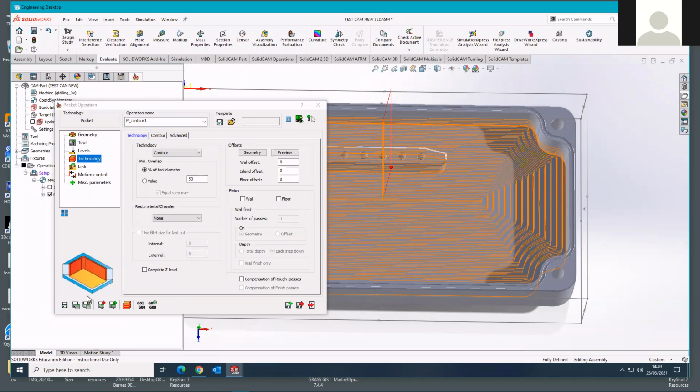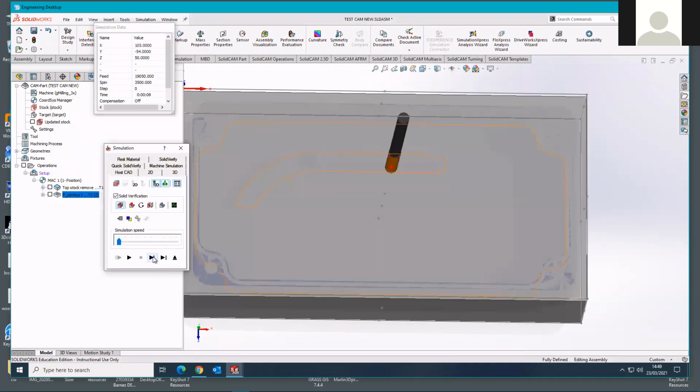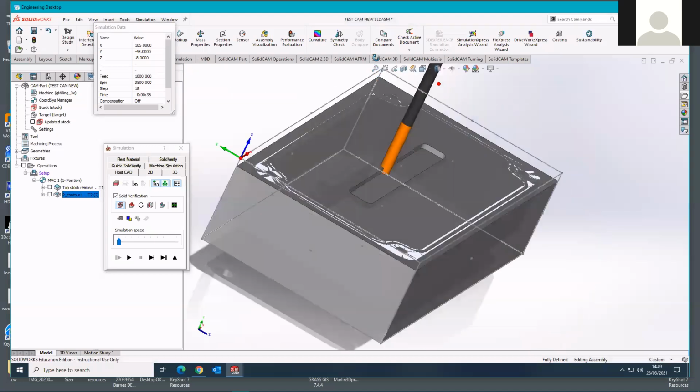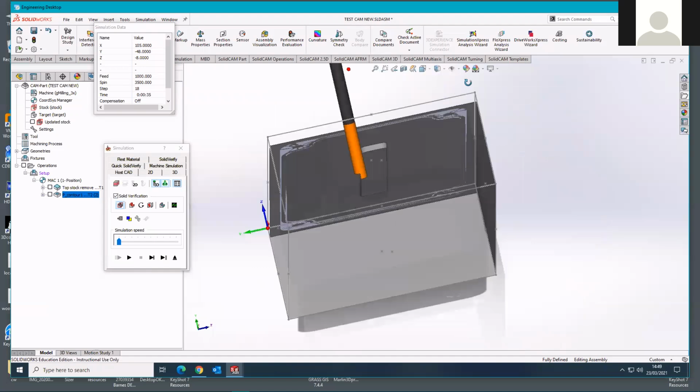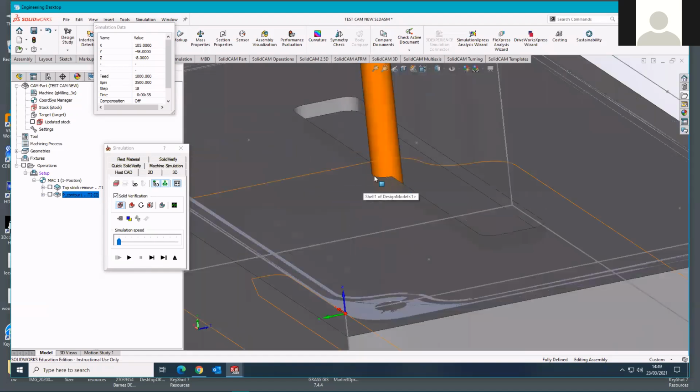So when you think you're removing material and you believe the tool should be held vertical, the actual condition on the end of the tool is that it's not vertical. It's been deformed slightly, like a banana shape. So it's been pushed away from where your program thinks it should be.